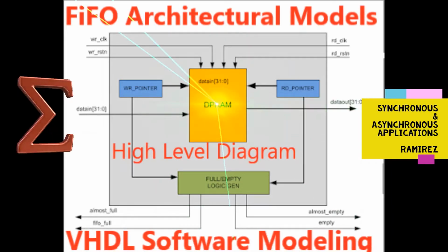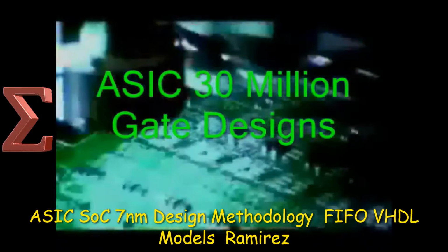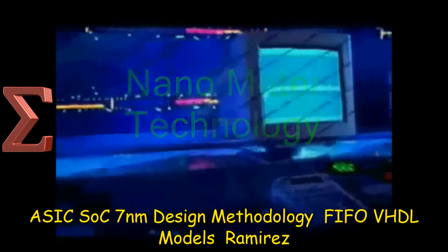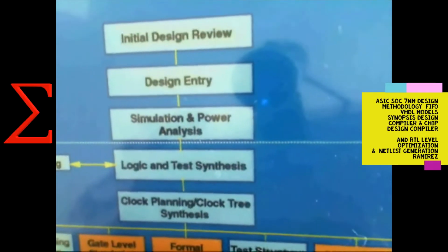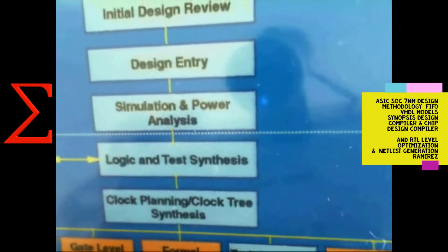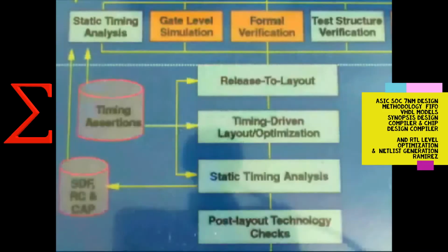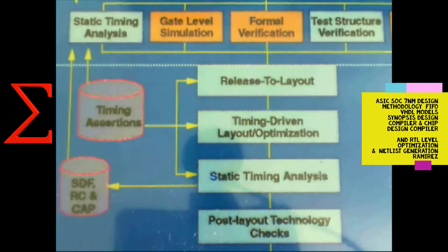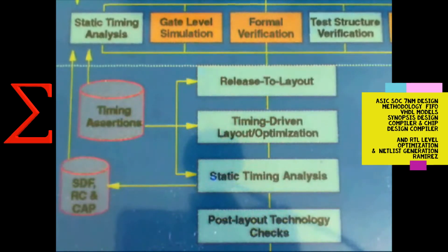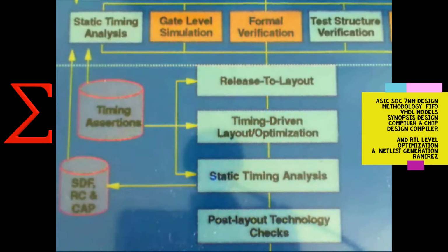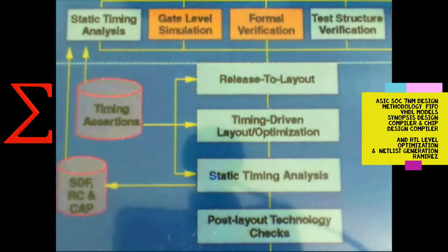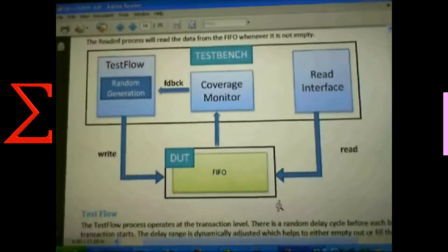The main objective of this framework is to develop and design an ASIC design flow using 90 nanometer Synopsys Design Compiler to generate the netlist of the physical design, and to use Synopsys ASIC compiler to perform the placement and optimization in conjunction, followed by clock tree synthesis, routing, and chip design.